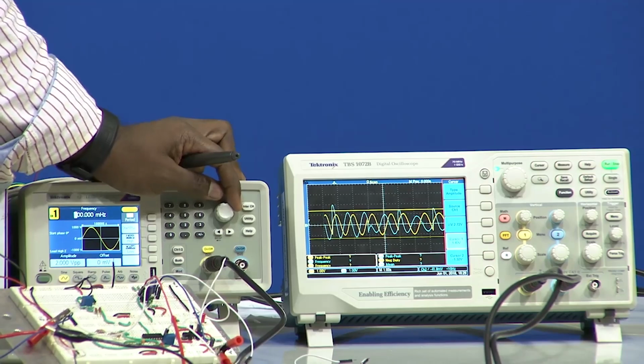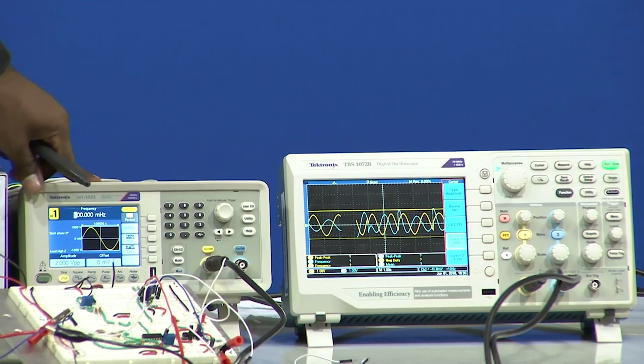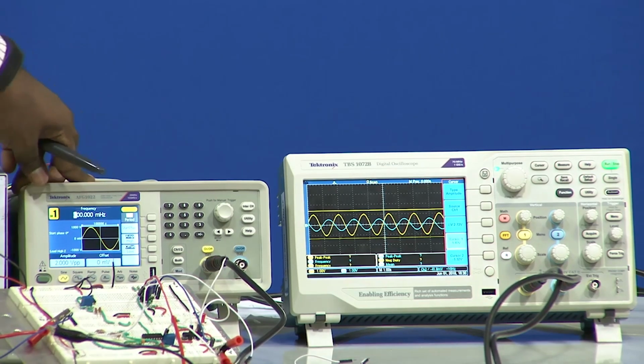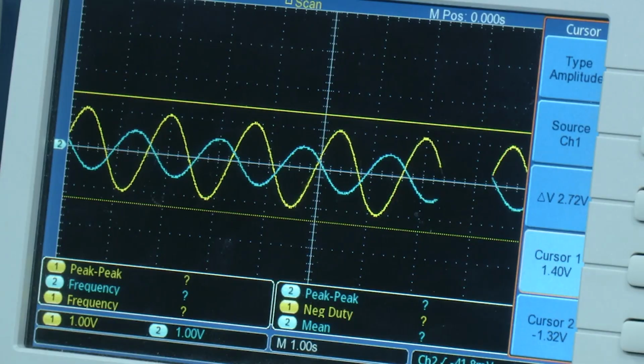So, one thing we can make clear is that for a high pass filter, below the cutoff frequency the amplitude will be attenuated. It will not be completely removed, but the amplitude will be attenuated from the cutoff frequency. And one more thing we can understand is that since it is a second order filter, we can see the drastic change when we decrease from 1 hertz.